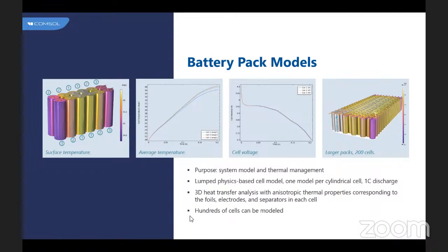And along the same lines, you can also do thermal runaway type of problems where there are various causes, short circuit, nail penetration, and so on, through which you can make one of the cells fail. Then, whether it's a gas venting or short circuit, the temperature of that cell can be captured as increasing, and then you can see how that particular high temperature progresses in the entire battery pack, and how you can design the cutoffs and a system which avoids failing the entire battery pack. So all those things can be done in battery pack modeling.